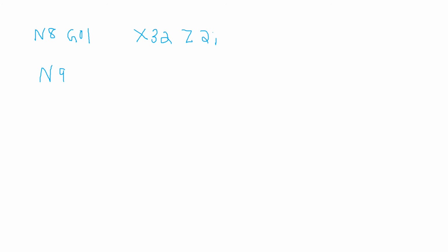So we went till 20, the last diameter reduction was 28, right? Now we will go 2 more, so it will become G01, sorry, X26. Then you will specify your z-axis, N10 G01 Z minus 30. Okay, and then you go till 30, and again the same thing repeats.